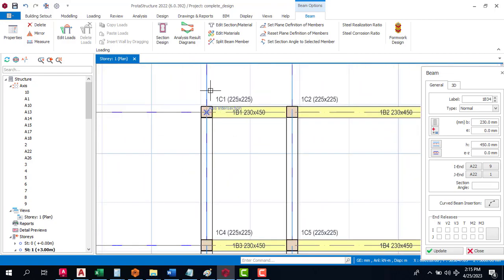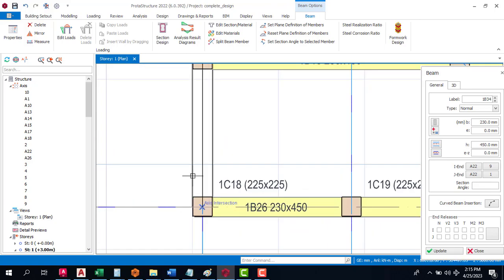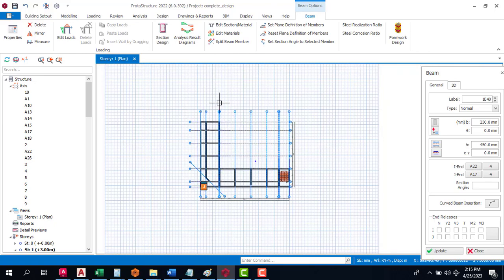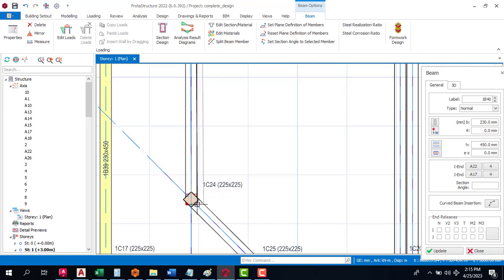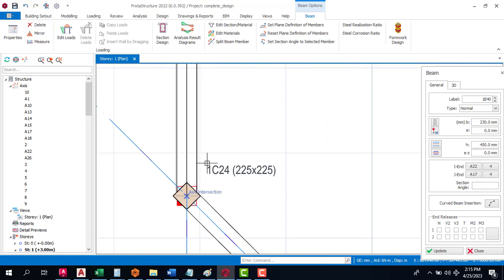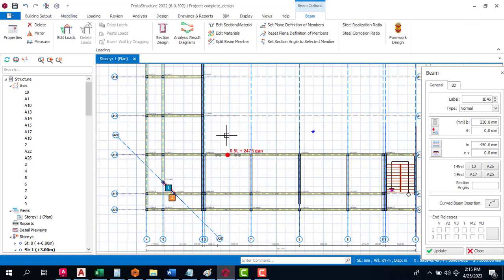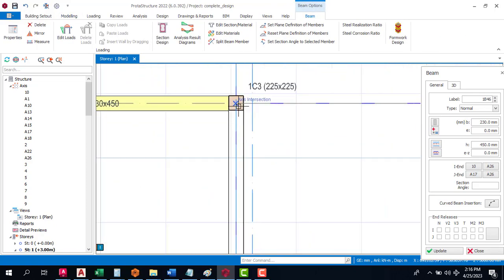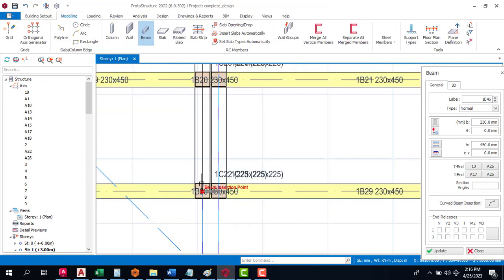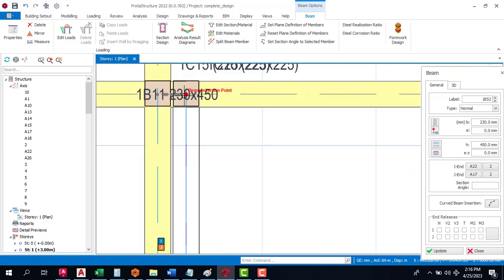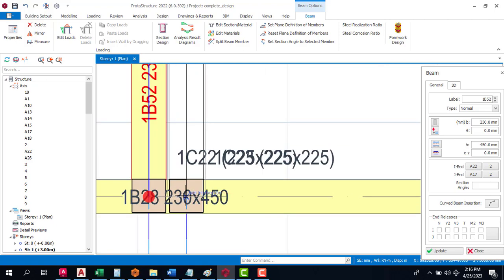But I learned that there is a little change now, that the span can even go more than 30 meters, although I stand to be corrected. I still maintain the 30 meter span in most of my designs. I learned it goes up to 40 meters now or thereabout, but based on what I used to know, it's actually a 30 meter span. So if you have a 30 meter span, it is actually professional for you to introduce an expansion joint, okay?